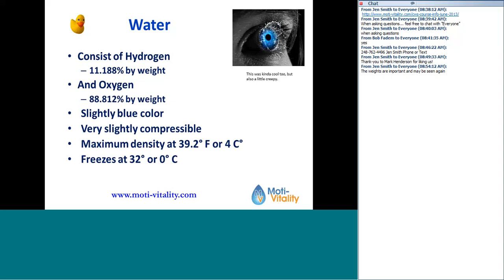That becomes important when you're looking at technologies like filtration or when you're backwashing something. That means that the colder the water, the more dense it is. That means that it takes less water to lift a bed up. You have to have less water pressure. The colder the water, the less water pressure to lift that bed up, because it's thicker, so it lifts stuff easier. Water boils at 212 degrees Fahrenheit or 100 degrees Celsius.